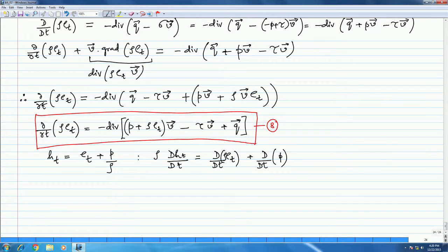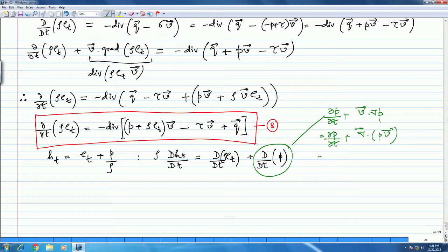Now if you look at this term here, the last term, which is essentially the total derivative of the pressure, what I get here is this is going to boil down to del P del t plus grad P, so del P del t plus grad of P. And therefore we can get this as divergence of PV. So total derivative is nothing but divergence of PV. So therefore I can write this term in the equation, I can write that.